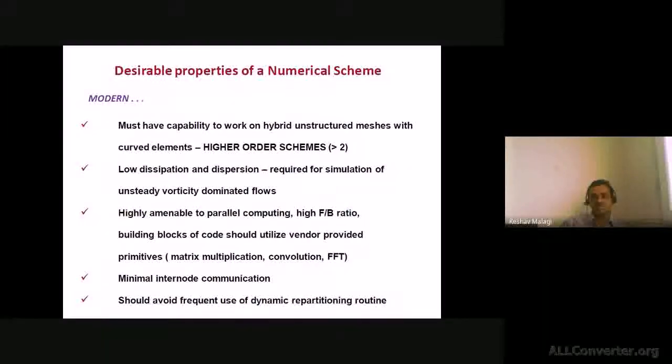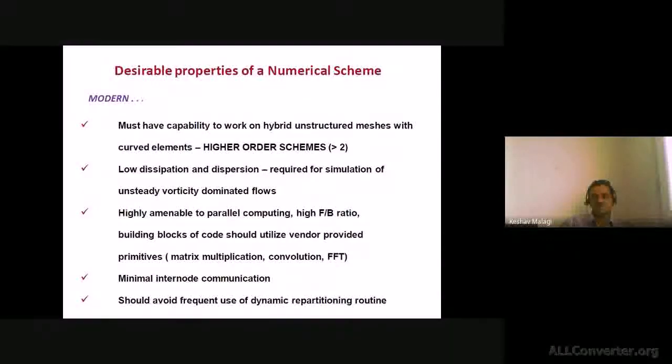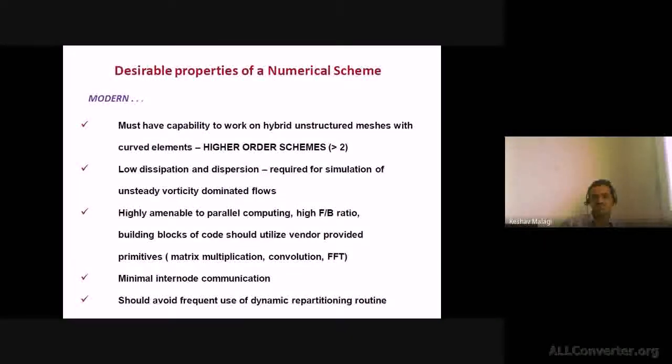Low dissipation and dispersion. When you are dealing with flows like vorticity dominated flows, the scheme should be very less dissipative, so that you capture the transport of vorticity, and dispersion should be less because the solution should not be distorted.